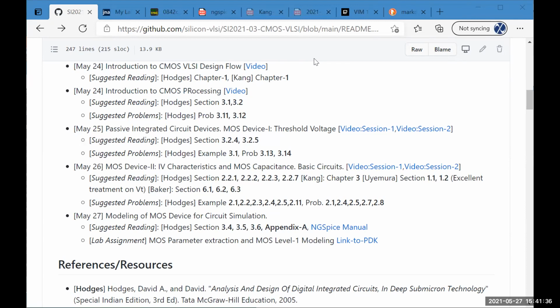So if you don't have it, then it obviously falls back to the default. If you have it in the model and don't pass it in your instance, it falls back to the model file. But if you have it in the model file and also pass it through the instance, then it'll fall back to that. Different SPICE simulators allow some model parameters to be passed and some not, but mostly they do. Okay, is that clear